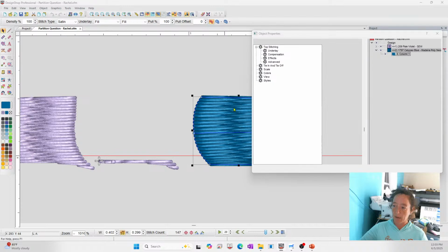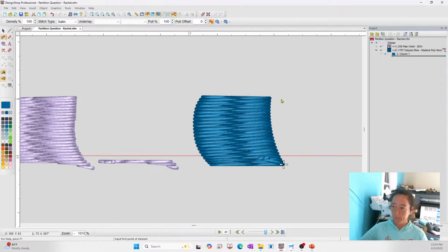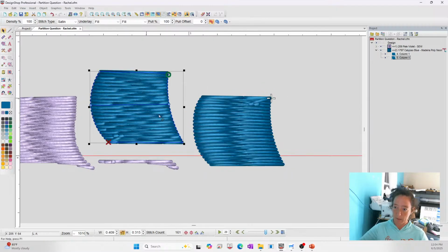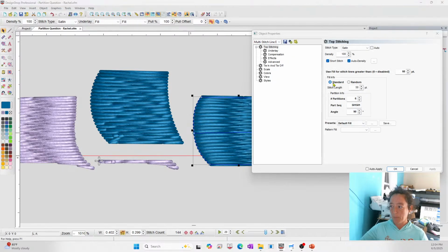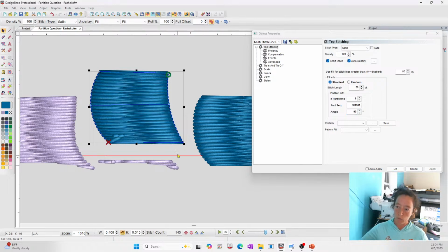So what is that? All right, so what I did was I created a column where I just click, click, click, click, click, click. Okay, so that gave me this, but how do I get this look to it? So that happens to be a partition of 6 with 501, 501. So if I come over here and I say, okay, let's make this a partition of 6, 501, 501, angle of 90, so it's 90 degrees from the edge, poof, you got it right there.